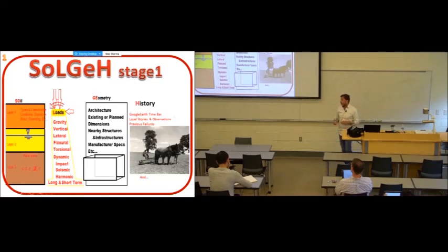Let's start with SOLG. SO is for soil, L for loads, G for geometry, and H for history. If anybody asks you any question regarding a geotechnical or even engineering problem, like give us your opinion on this problem, don't ever answer quick, because a quick answer is related to intuition. You don't want to answer an engineering problem with your intuition. Collect the data, sleep on it, think about it, come back with an answer after you do some calculations and